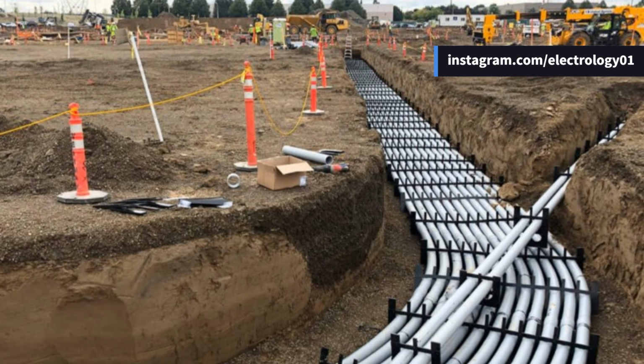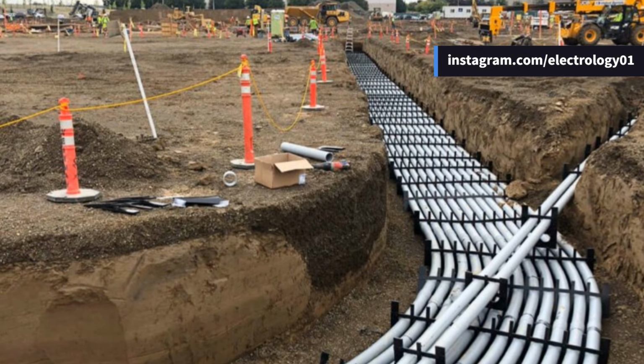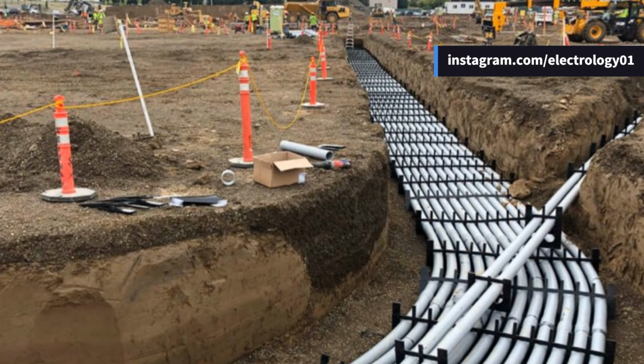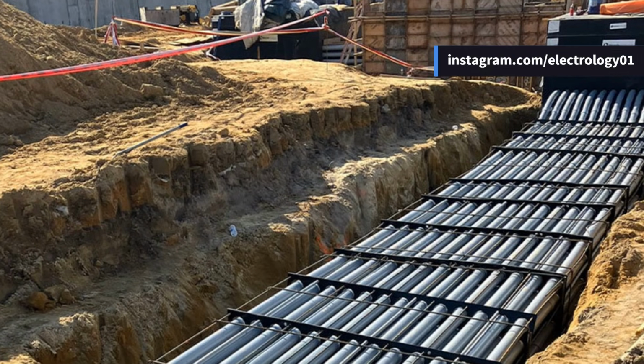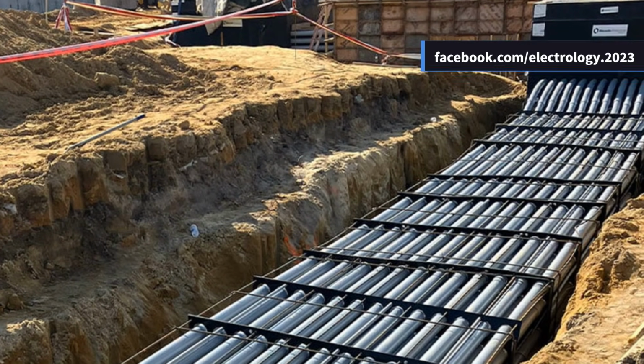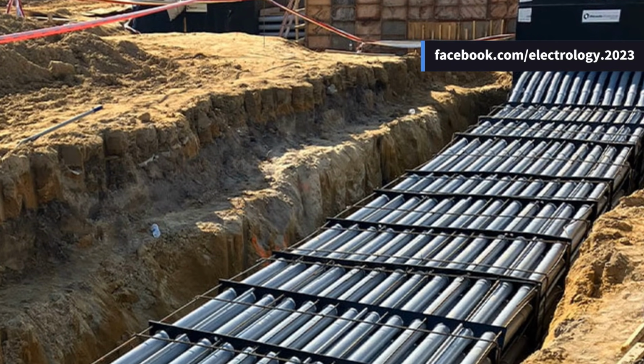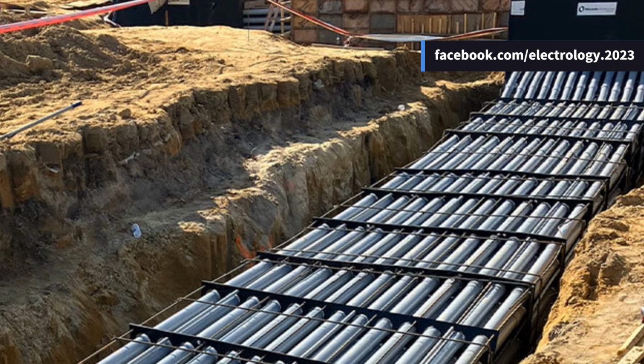As current flows, heat builds up. If the cable can't get rid of this heat fast enough, its temperature rises. For typical underground installations, the safe working temperature usually reaches around 65 degrees Celsius for armored cables and around 50 degrees Celsius for lead sheath cables laid in ducts.